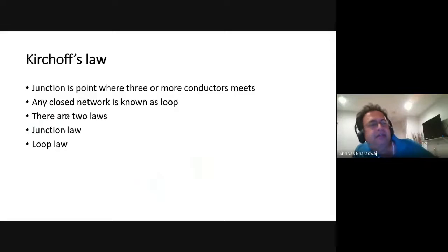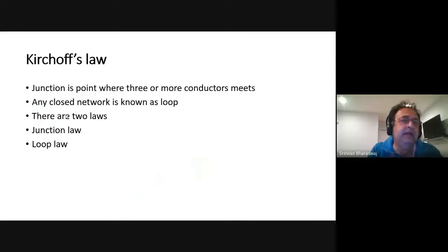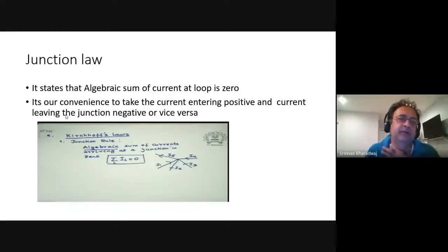The temptation will be to sometimes not do justice to the number of equations and unknowns. The circuit solves itself, but the number of equations and the number of unknowns are very typically exactly the same, right? You don't get more equations and fewer unknowns. The equations are all dependent. That is a very important point with Kirchhoff's law.